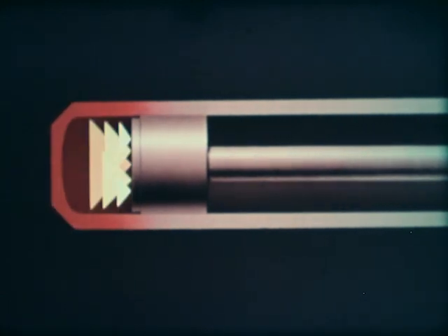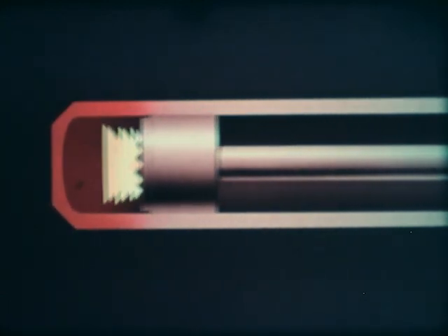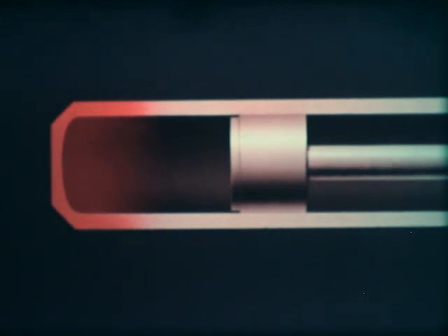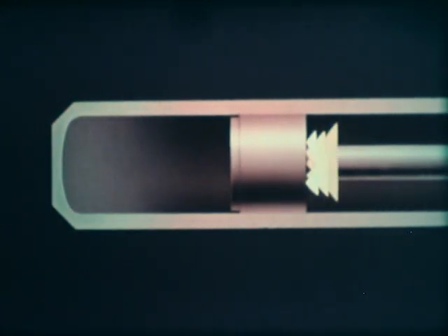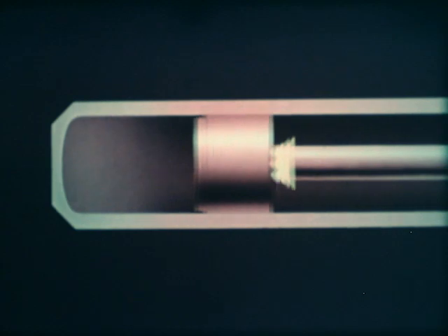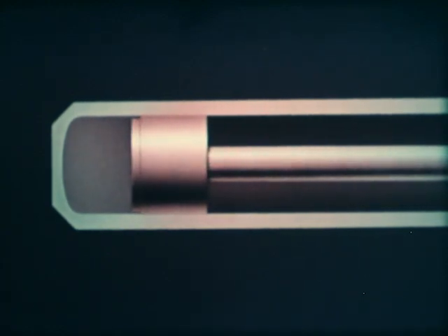The power can be increased by raising the pressure on both sides of the piston to a larger value. In the Phillips engine, this may be 100 atmosphere or more. The forces induced by heating and cooling will increase correspondingly, as will the energy delivered per cycle.